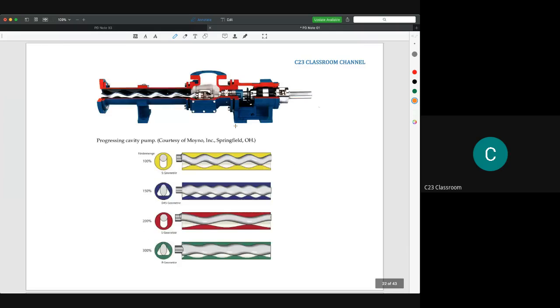And then this is a cavity pump. This is especially to move liquid that is very slurry, for example toothpaste or something like that. We cannot use a centrifugal pump, and sometimes it is not efficient to use a piston pump, because the way we move slurry liquid is by moving it in slow motion.